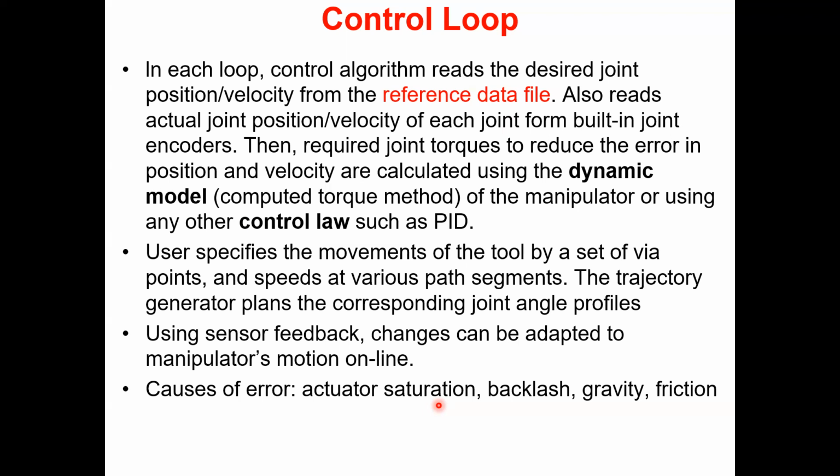Gradually, the servo controller gets an increasing demand to drive joint 1 or 2 or 3, whatever, within 10 milliseconds, and the actuator tries its best, but within 10 milliseconds it cannot actually cover that angle. So it goes to what is called actuator saturation.